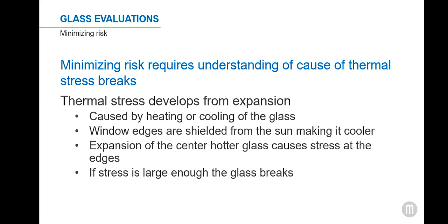A clean cut edge is the strongest, as the cutting produces the least amount of damage. A polished edge is the next strongest. The actual edge strength depends on the quality of the glass edge. So if there is damage to the edge, this will reduce the strength and increase the likelihood of a failure due to thermal fracture. The probability of breakage becomes significant with damaged edges.